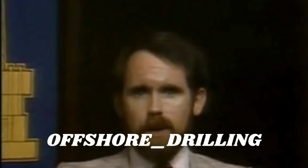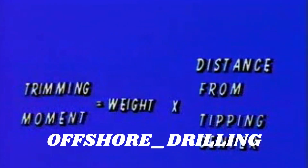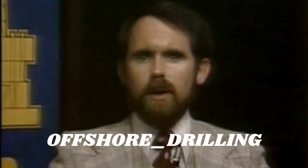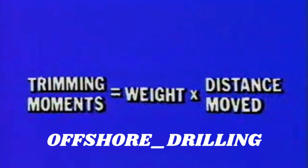The force which is causing the vessel to trim about this tipping center is called the trimming moment. In loading or discharging, this moment is determined by multiplying the weight of the material times the horizontal distance from the tipping center to its stowed position. We use a similar procedure when we shift cargo or equipment that is already on board. In this case, we multiply the weight moved times the distance moved, forward or aft, to obtain the trimming moments.